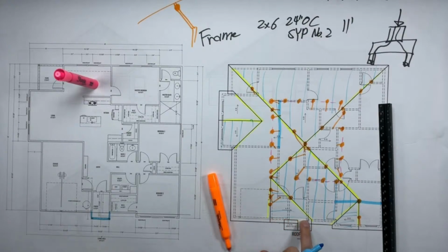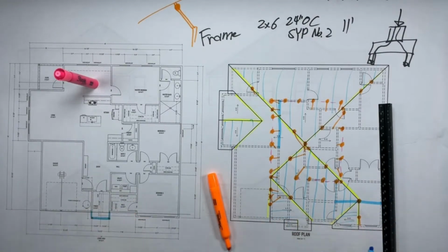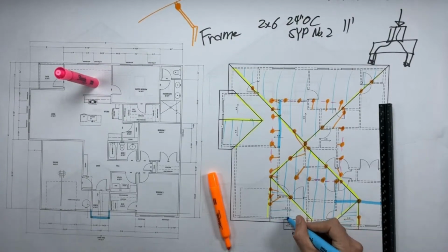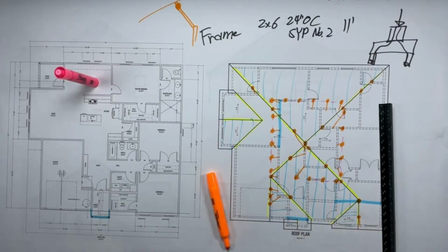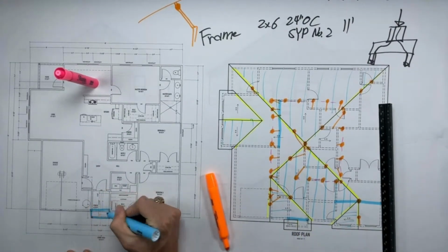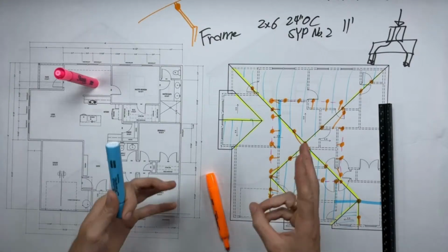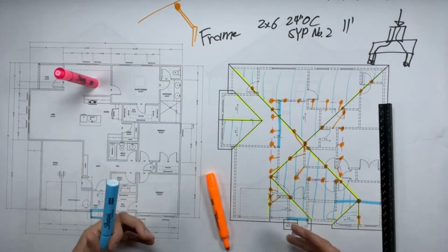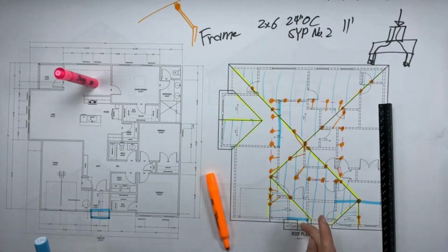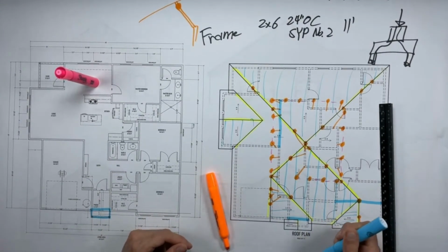But what's happening underneath this one? Well, you could do it a few ways. You could double or triple up the rafter that runs right here and basically make a little beam, or you could put a beam directly below this. That would be another way of doing it. If you just want to keep it super simple, you just put another beam in there. When I say beam, it's going to end up being tiny. You could probably use some two 2x6s and that would be structurally sufficient after the math, which I showed you guys how to do the last 2 Fridays. So shout out to that. All right, cool. We're good there.